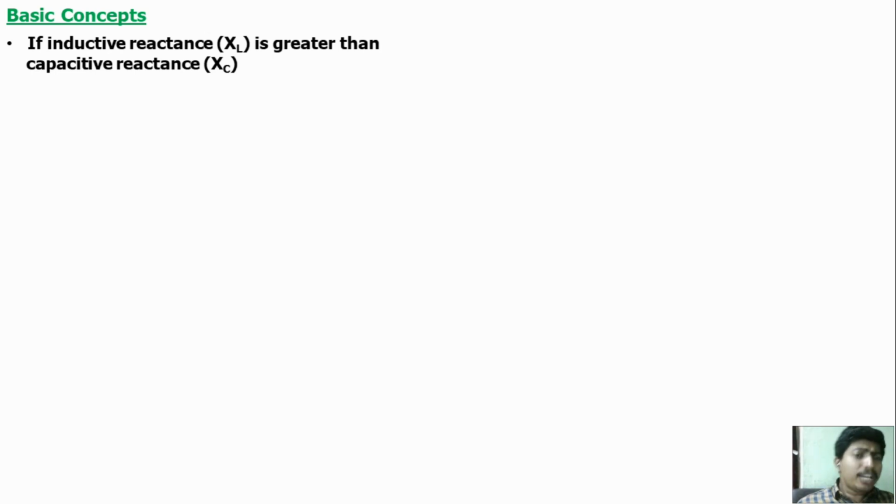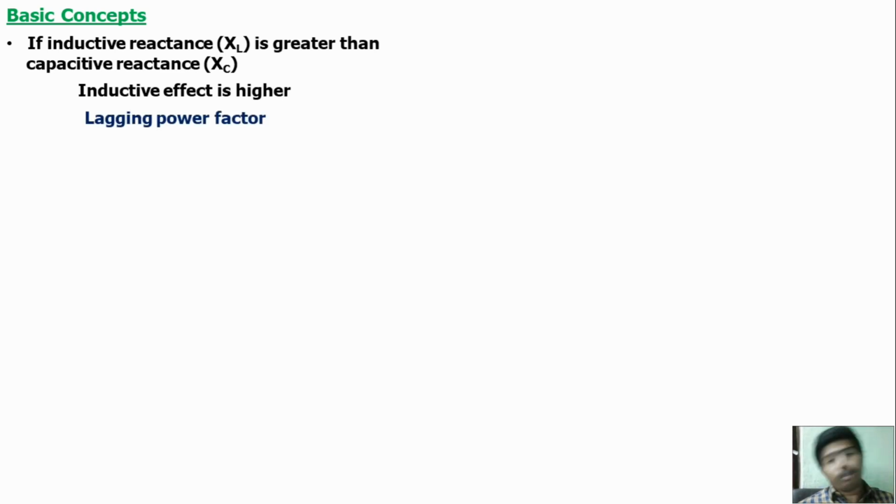If inductive reactance XL is greater than capacitive reactance, here inductive effect is higher. So lagging power factor. Inductive effect is higher means lagging power factor. Another point, in RLC circuits, we know that impedance Z is equal to R plus j(XL minus XC).